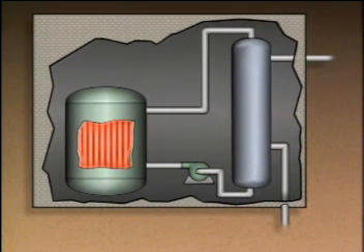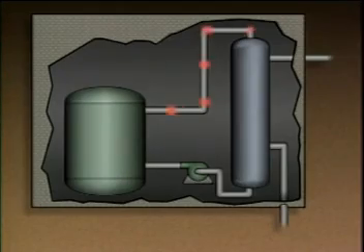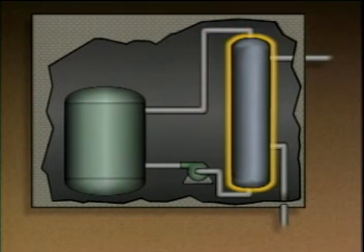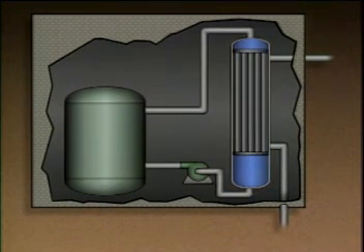This heat is transferred to water that is flowing through the reactor. The water is under high pressure so that it will not boil and change to steam in the reactor. The heated water is pumped to the steam generator, which is basically a heat exchanger. In the steam generator, the heated water from the reactor passes through tubes and gives up its heat. Water at a lower pressure flows around the tubes and absorbs the heat.